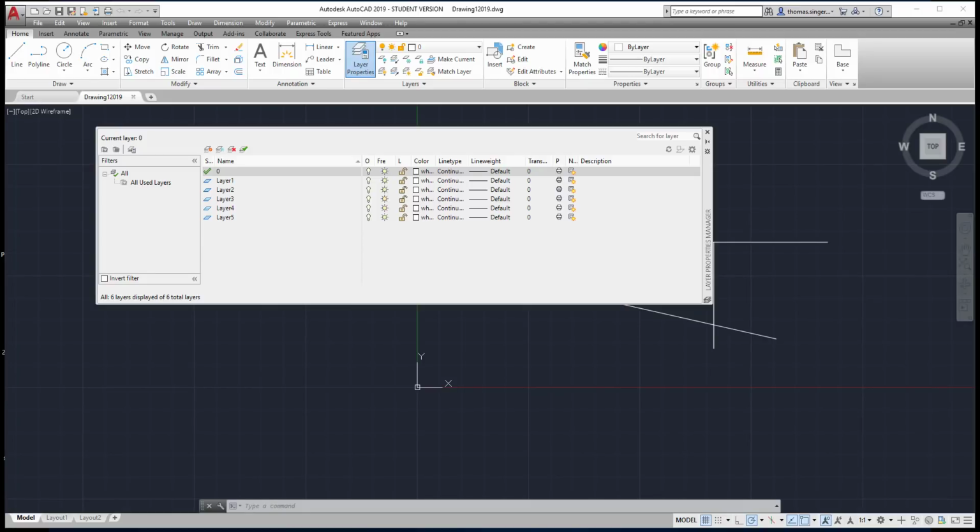You saw that I didn't have the layers on the previous screen, and now magically they appear. What happened was that I needed to restart AutoCAD and have the layer names appear, because as I was clicking new layer, this was totally blank in this space. All I did was close the drawing and reopen the drawing, and the layer names reappeared. Again, that was just an odd configuration component. So if that happens, just close the drawing, reopen it, and everything should be good.